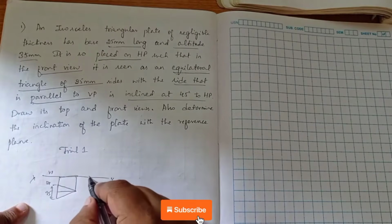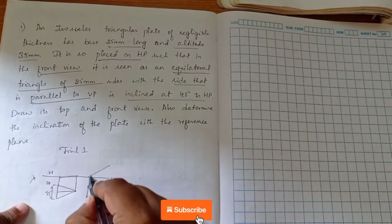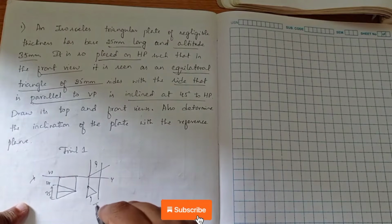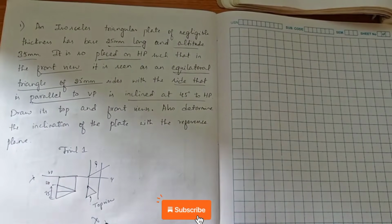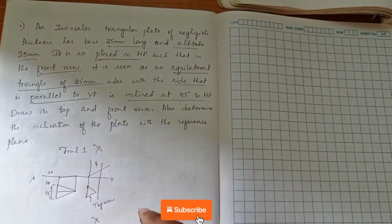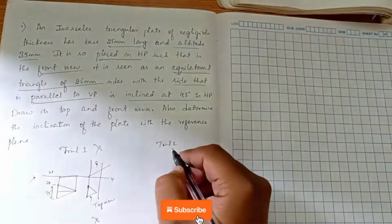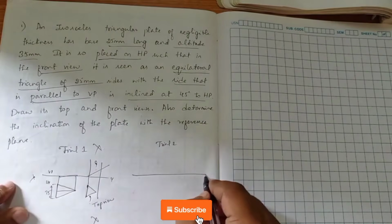Now by inclining this we'll get an equilateral triangle here. We will construct it, then by projecting here we get the angle. But here you can see this equilateral triangle we are getting in the top view. This is wrong because we have to get a front view. So this trial is wrong. Similarly, we'll go for trial 2.